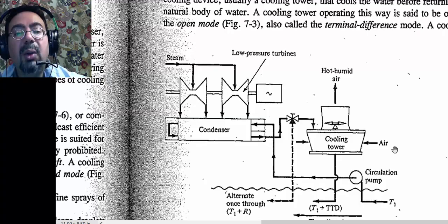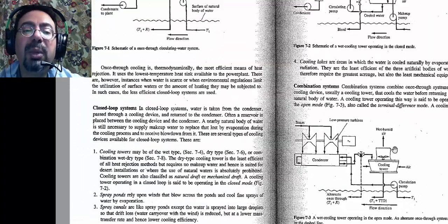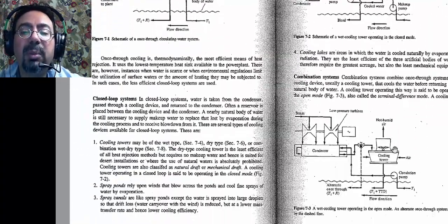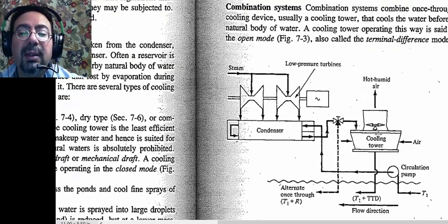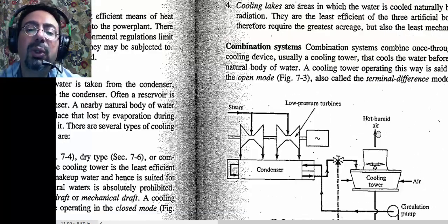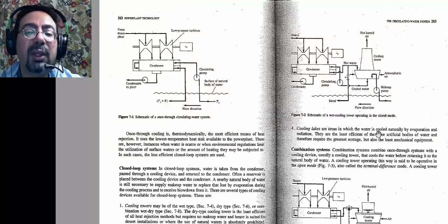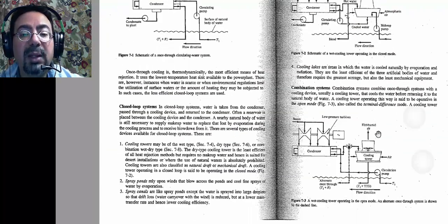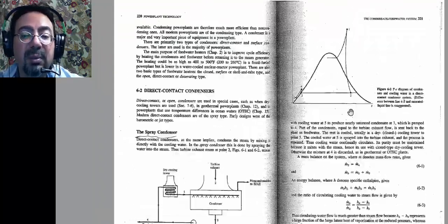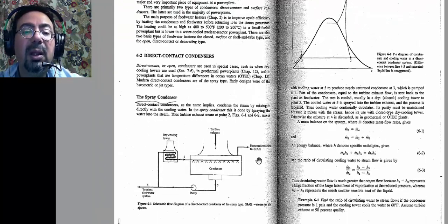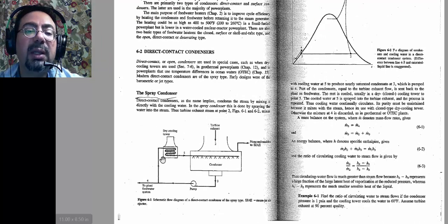Okay, so now the cooling tower, whether it's going to be really huge or whether it's going to be short, that will determine whether you need a fan to help or you can just do it all by natural convection. Okay, so short ones will have fans associated with them. Alright, this is the part when we say it's a wet bulb.